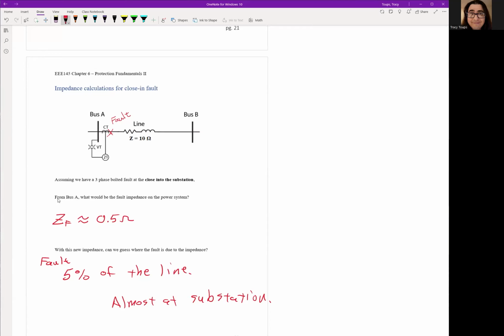And so again, it's good. The nice thing about this relay is it can tell if a fault is within my transmission line or not. So for example, if we have a fault really far down the transmission line, the impedance is going to be higher than 10, so we can sense that maybe this is not our line, it's somebody else's line, somebody else's problem. So maybe we should hold off before we act. Remember, I'm mainly responsible for my transmission line, not the ones five lines over or in the neighboring utility.